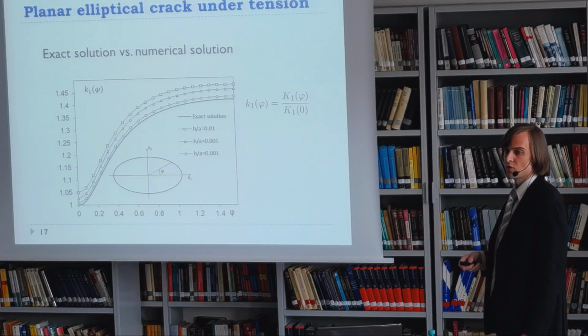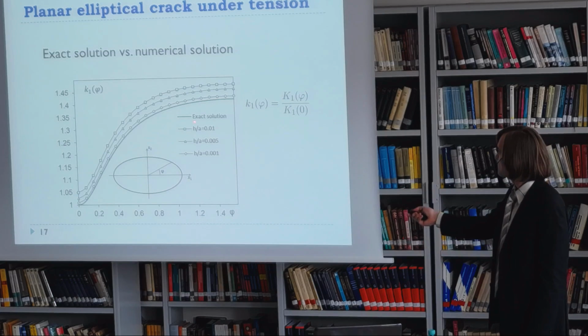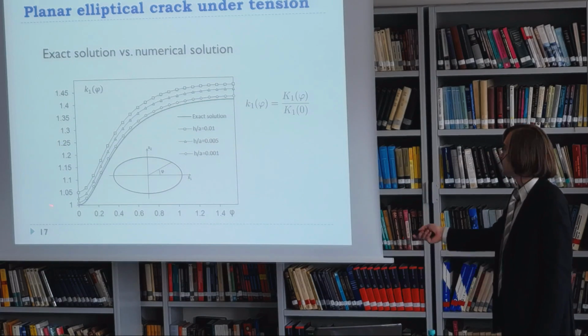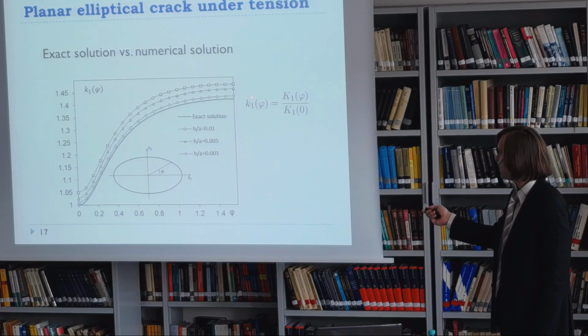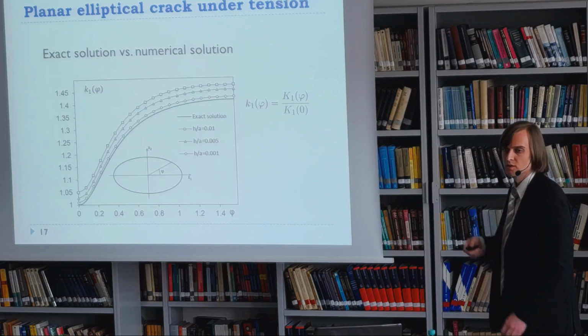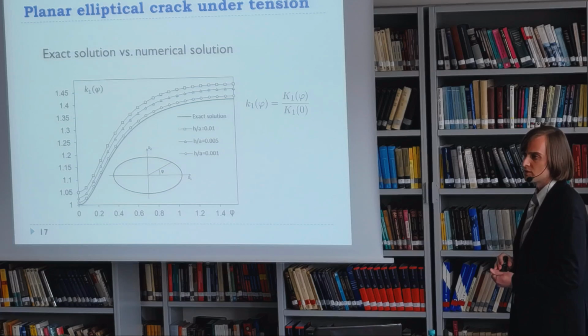This is the convergence of the method, of course, for different node grids. Of course, for smaller node grids with smaller step, our stress intensity factor on the crack boundary becomes closer to the exact solution.